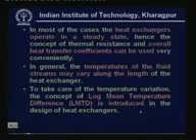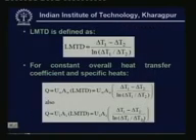So to take care of this temperature variation along length, a mean temperature is defined. This is known as log mean temperature difference, or LMTD. So we have LMTD introduced, and it is very widely used in heat exchanger design. This LMTD is defined as LMTD is equal to delta T1 minus delta T2 divided by ln delta T1 by delta T2, where delta T1 and delta T2 are the temperature differences between the hot and cold streams at the inlet and outlet respectively. So one can be inlet, then 2 will be outlet, or vice versa. Okay, so they are basically the terminal temperature differences between the two fluid streams.